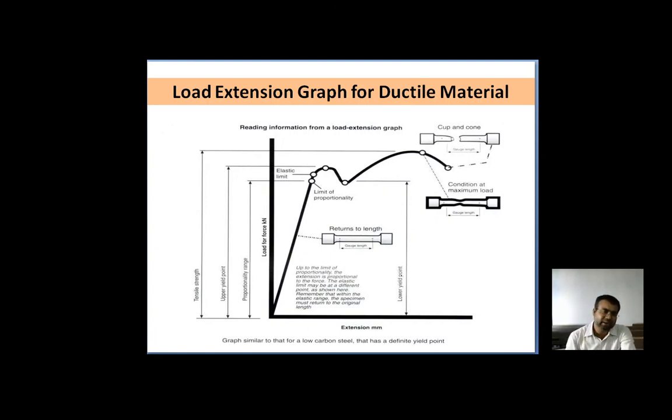Now, what is the yielding of that particular material, in low carbon steel and the many linear polymers? The stress-strain curve shows an initial maximum, followed by a lower stress, as shown in that particular figure. And after the initial maximum, all the deformation at any instant is occurring within a relatively small region of the specimen.